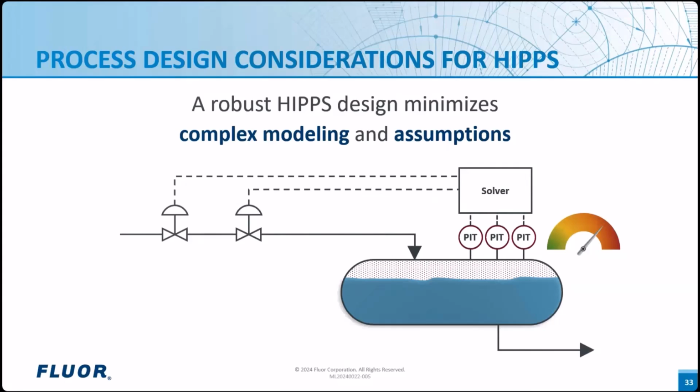If a pressure controller to flare was present, it would open and remove any pressure to level correlation. Predicting how fast the pressure rises upon the instantaneous moment that the liquid overfill occurs is even more complicated and not worth attempting. While the pressure transmitters may have been easier to install, upon review and assessment, it's clear that using level transmitters as the initiator would provide a more robust, simple HIPPS design.